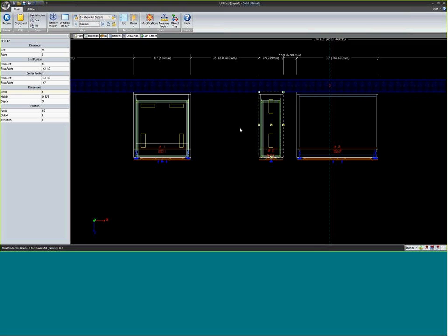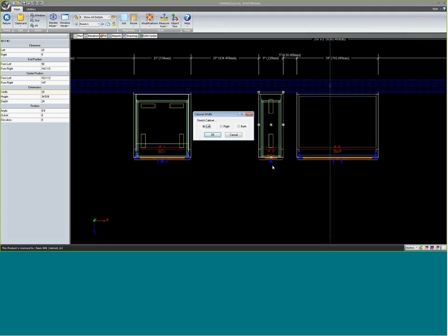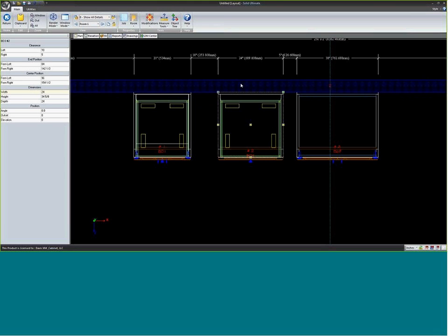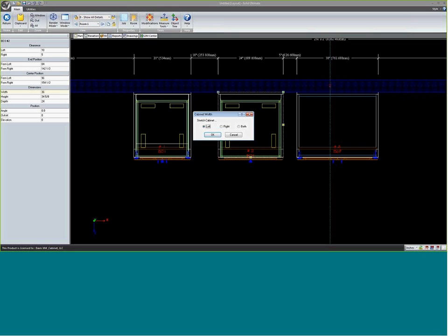So what you can also do is just come over here and either click in that cell, or if I click on cabinet, notice highlighted yellow over here before I even click. If I just type 24 inches and then hit enter, it's going to ask me which way do I want to stretch this cabinet. I'm going to tell it to the left. So it's stretch cabinet to 24 inches to the left. If I told this now to go, let's say 36 inches, but I'm going to this one to the right, it says at me here.